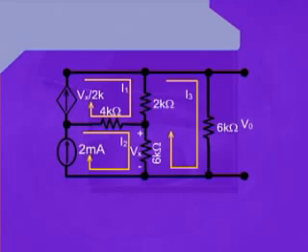And the bigger mesh, which is onto the right hand side but before the output terminals of the circuit, we assign it the name as mesh number 3, and respectively we consider that the current I3 is flowing through this mesh as well. Now, for our convenience, I have also assigned all these currents flowing through individual meshes in the clockwise direction.